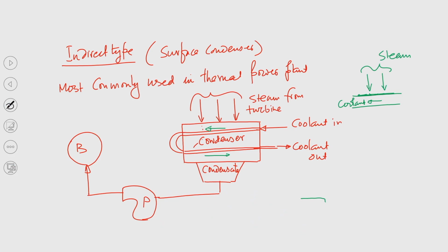When steam is condensed, it condenses in the form of a drop and eventually is collected in the condenser chamber, but the leakage air will also try to condense in the form of a film, and that film will reduce the heat transfer rate, because a thin film of air will not allow the coolant to receive the heat from the flowing steam.